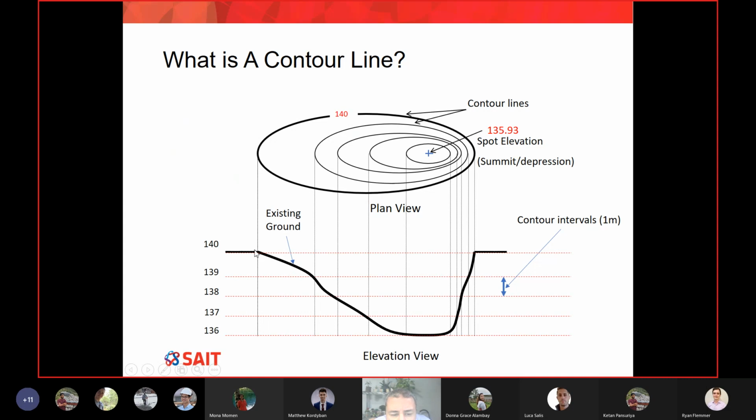Please look at this. Here you have a slope, and here you have another slope. Go back and look at how the contour lines are behaving here and here, and you will know our first rule. Our first rule is very simple. When contour lines are well spaced, it means I have a mild slope. When contour lines are very, very close, it means I have a cliff, an almost vertical side. And we can apply this rule here.